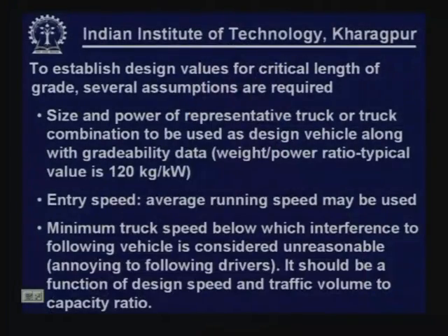Obviously, what is annoying will depend on the design speed for which the road is designed. So, the minimum truck speed will depend on the design speed and also the volume to capacity ratio.